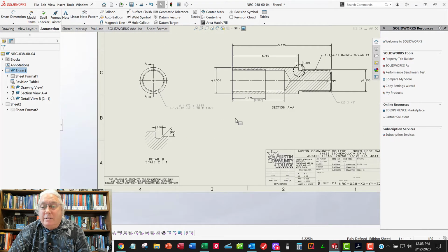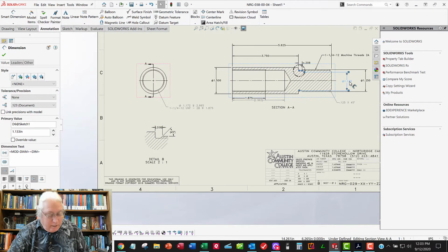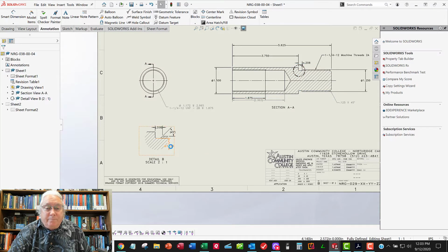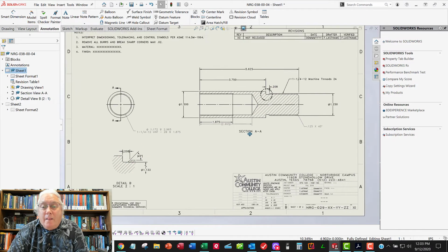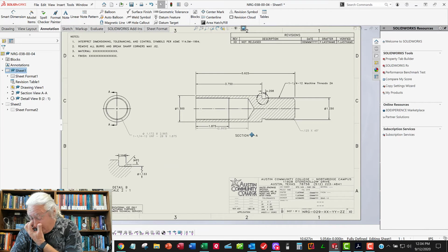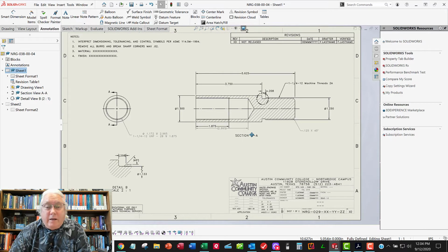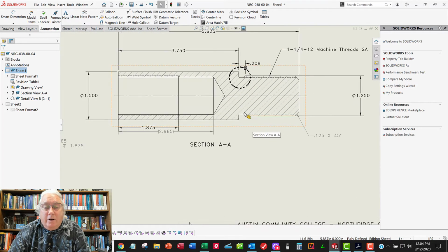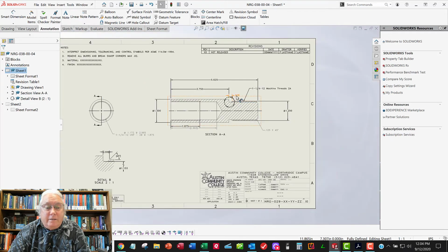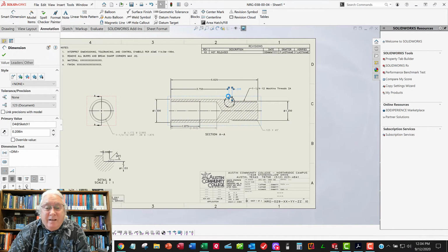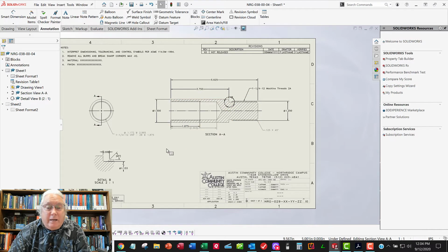All right, so maybe I've changed my mind. I think I might want this guy to really be over here because it belongs with this thread relief. So maybe I'll drag him back over here just for fun, and I'll need to do my jog thing again. All right, now what? So we took care of the note callouts, so let's do our thread callout, or excuse me, a thread relief. So let's just add a note over here to specify this thread relief.